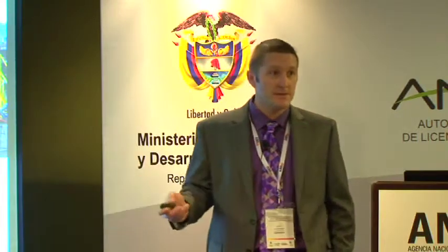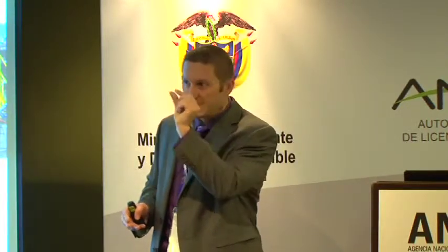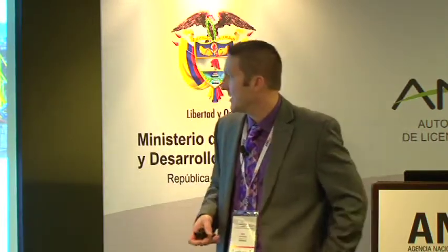Between maybe 5 to 10% of the mixture is going to be sand or other proppant to hold open these fractures. If you were to pressurize the shale and then relieve the pressure, the shale more or less is going to close back up on itself. I mean, it might stay open somewhat, but it's going to pretty much close back up. And so what the proppant does is it keeps those fractures open. So if you can get a couple grains of sand in between those fracture faces, that's just enough of a width of an opening to allow the gas to flow out of the shale formation.